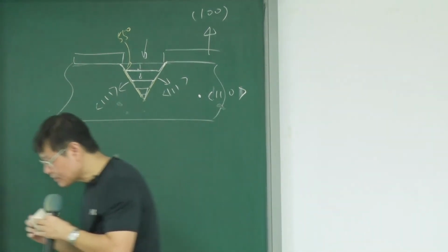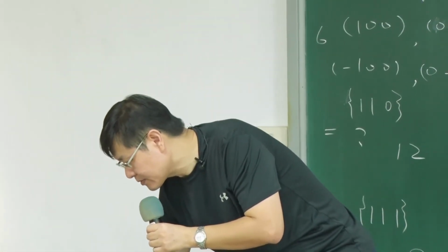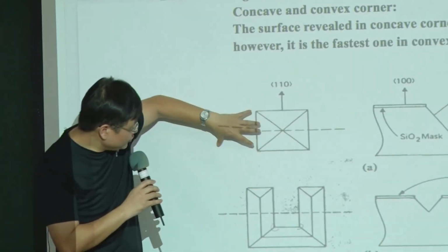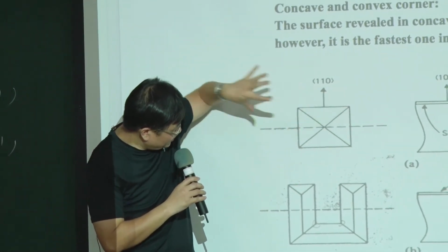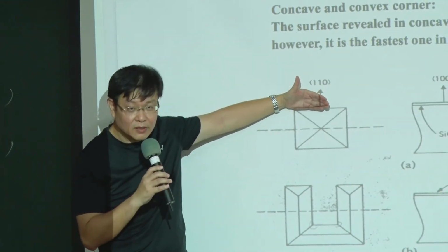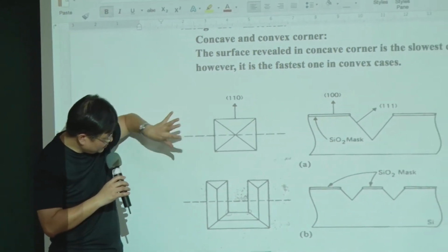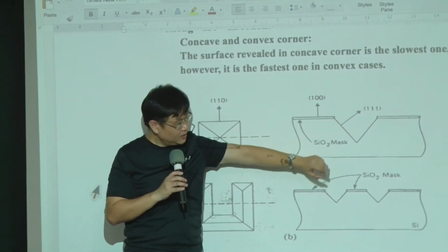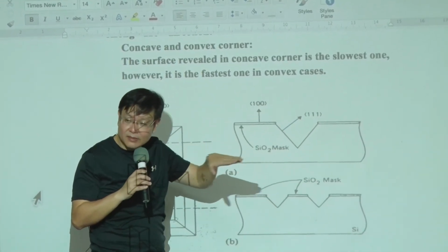But those things happen only when this full surface, originally we punched the hole, it's a rectangular hole. So you can see this full surface, and when we etch down, the 111 surface will appear gradually, right? Because your etching stops over there. So finally it forms the pyramid structure, like I drew over there. You go step by step, okay? So if you don't etch until the end, you take it out at some time point, you still will find a flat surface on the bottom.